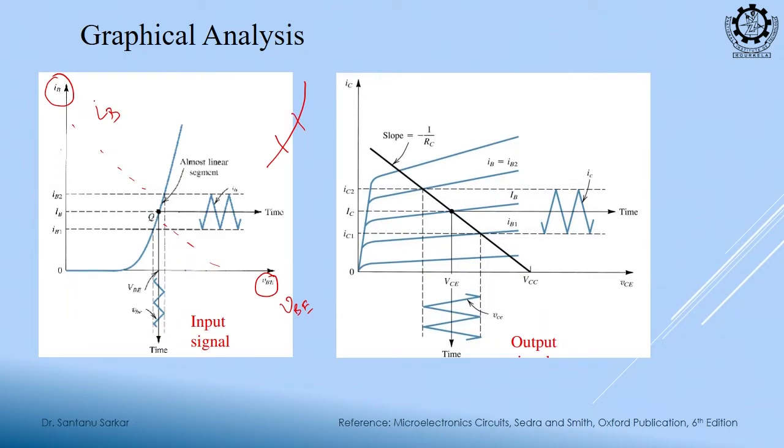Okay. So, how are we approximating? See, what is our objective? Our objective is to make it as simple as possible. Now, in general BJT is a nonlinear device, the current nature is exponential. Now, how are we approximating it to a linear equation? We are assuming that this is a very small portion, right. So, what is the first condition? That within this small portion, if your input is varying, now this small VB is your AC signal.